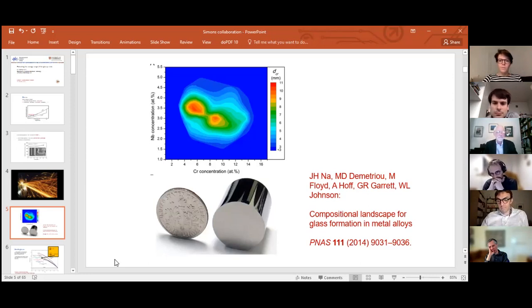Okay. And is it able to crystallize towards the center because the composition then changes? By and large in these systems, if you were doing this with conventional metal casting of alloys, for sure you would have segregation of elemental components. In these systems, by and large, you don't, except on a very local scale. So I don't expect any difference in composition across the cylinder.